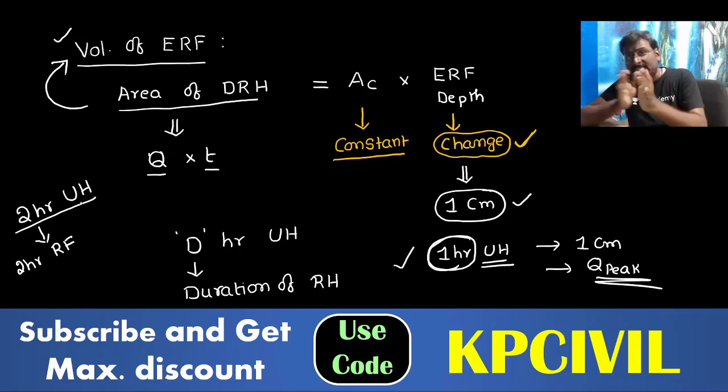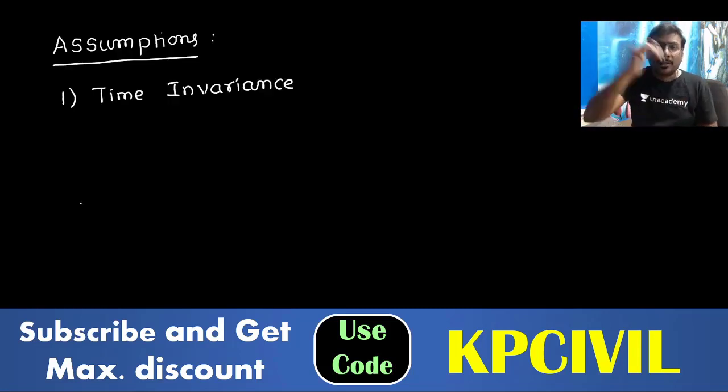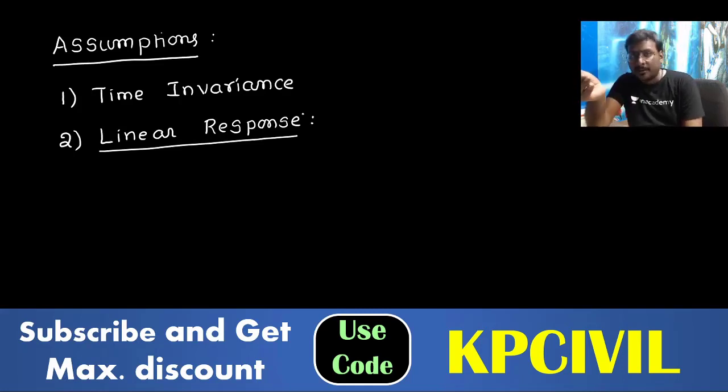You have plotted a 6 hour UH. 6 hour UH is for 6 hour rainfall. In future, any 6-hour rainfall you can apply it. That is called time invariance. Second one, linear response.